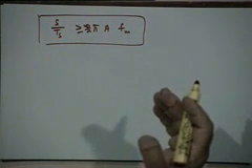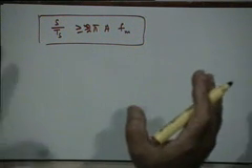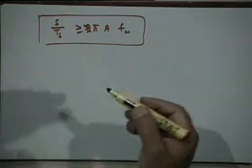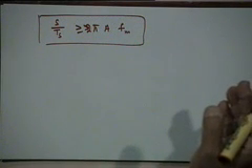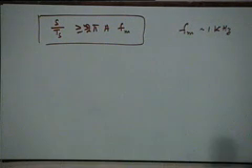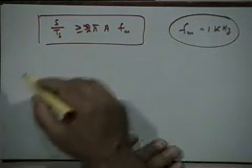So for voice signals, it is sufficient if you satisfy this condition at some pre-chosen frequency, where the amplitude has a certain level which is typically known to be large. Voice signals actually have many frequency components, it is not a sinusoidal signal, but just as a design method, you typically choose F_M to be in the neighborhood of 1 kilohertz, although your actual voice signal goes up to 3 or 4 kilohertz. So you have to ensure that the slope overload does not occur here.